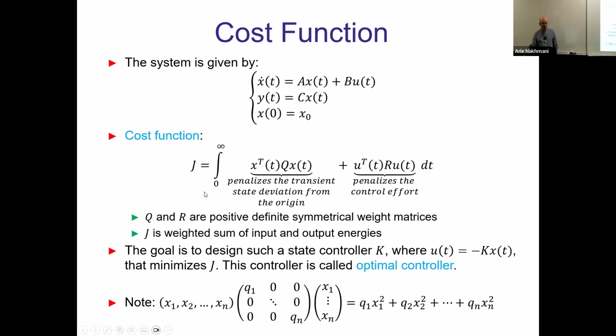The goal of the optimization is to minimize J, to get J as minimal as possible, okay? And you have relative weights of two components here. We will call them Q and R. Think about them as relative weights between these two parts: one part will have importance Q, another part will have importance R. So if you increase R a lot, you make it 1 billion, you get 1 billion times the energy of the input plus some small number times the energy of X, some kind, okay? And you want to minimize that sum.